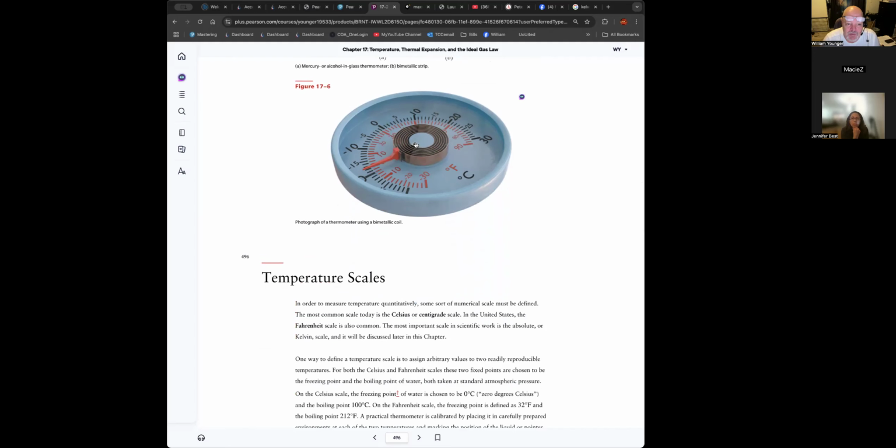They actually have this bimetallic strip mounted, fixed right there, and then the material goes around and around and around. It's just a big spiral because it turns out these changes are very small. The coefficient of linear expansion is on the order of 1/1 millionth. So it takes a significant change before you get a significant change. Therefore, the longer the piece of bimetallic strip is, the more it'll move.